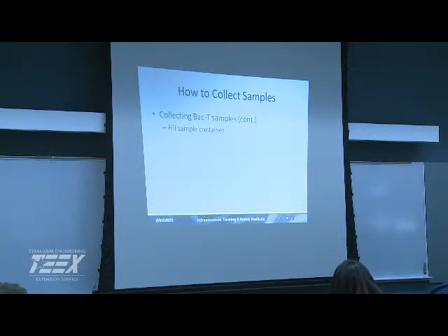But that's why we want to preserve our sample properly, right? Chain of custody is real important. If you're pulling your own samples, you need to document where you're getting it from, when you're getting it, your residual, things like that are important to have as a part of your sampling. Questions, comments? Need to have it there within 30 hours, so 6-hour hold time and 24-hour shipping, and then obviously